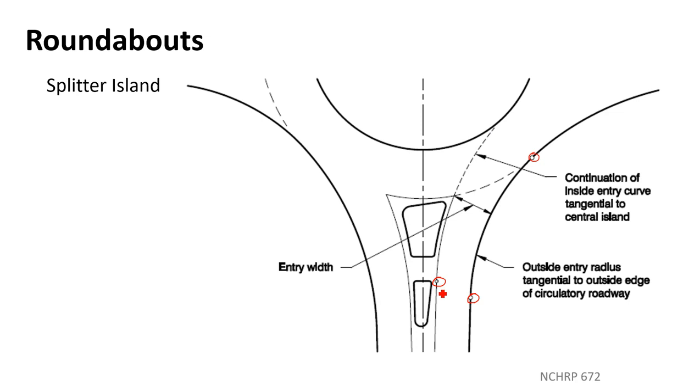Again, so this is tangent back here, right? Here's tangent. That was much better through there. And then these are not the same. They're not only not the same radii, they have a different center of radius, and so that brings out this width here, right? We widen out versus what the lane coming in was.